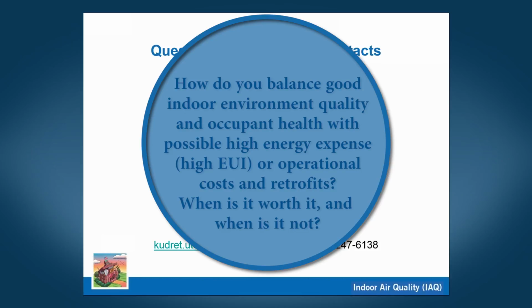I have an example of people overreacting and running buildings 24/7 with outside air dampers wide open in order to mitigate that. And again, as Bill pointed out, with 100% outside air, you might actually be causing more problems with moisture or too dry air and so on and so forth. So to balance, we go to indoor air quality first. There are so many things in schools contingent on that.